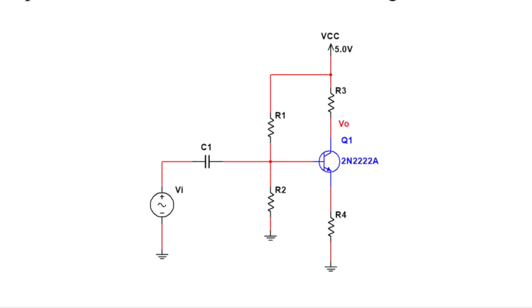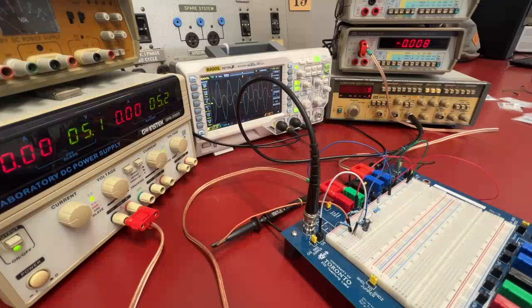You should be careful with the base voltage. The ratio of R1 and R2 is important, mainly to generate that specific voltage. However, you should avoid using extra large resistors for R1 and R2, as in that case the voltage will be affected by the base current of the transistor. So resistors in the range of, for example, 10K should be fine for this specific implementation, or even 1 or 2K. Here you can see an implementation of the amplifier.